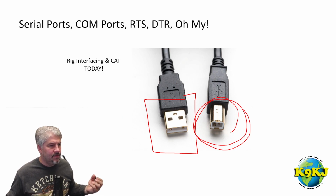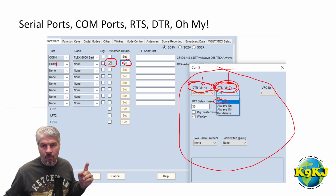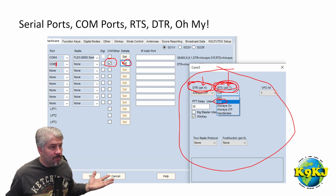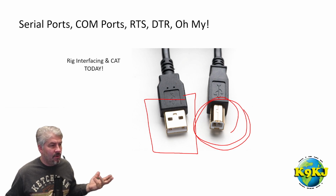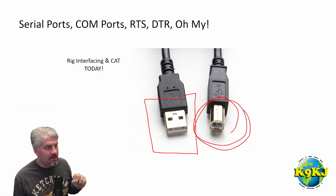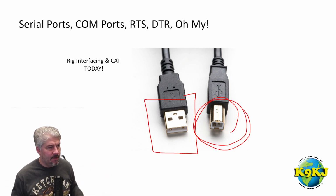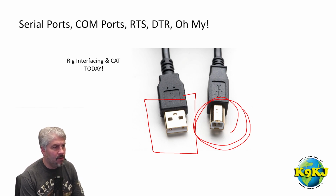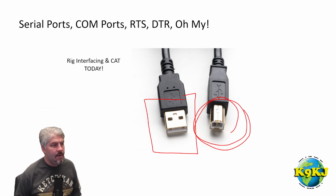So that's why we still talk about RTS and DTR today, because we still have that callback to the old days where we actually used pins, where you can see there's pin 4 right there, or pin 7 on a serial cable to actually key the radio. Now we don't really need to do that anymore. However, we utilize those methodologies to interface the radio and the software, and to have some commonality to talk to each other. So that's how that works, and that's how that went. So a little bit of history, and